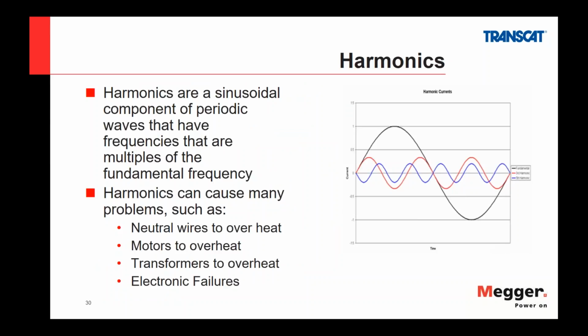Now, harmonics are a sinusoidal component of a periodic wave that have frequencies that are multiples of the fundamental frequency. So here in the United States, the fundamental would be 60 Hertz. The second order would be 120 Hertz, third order 180 Hertz, and so forth.